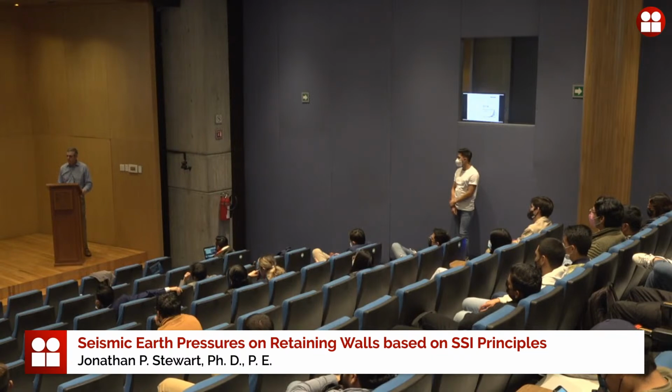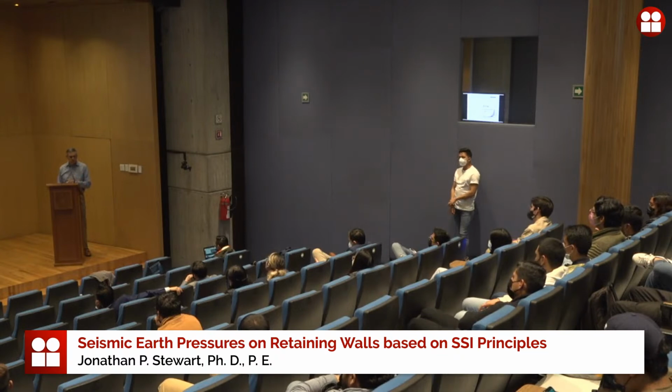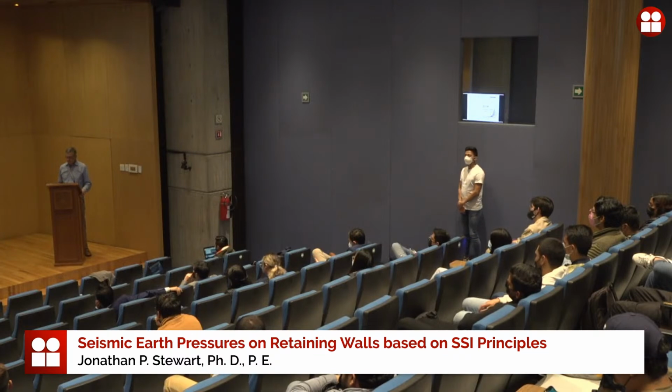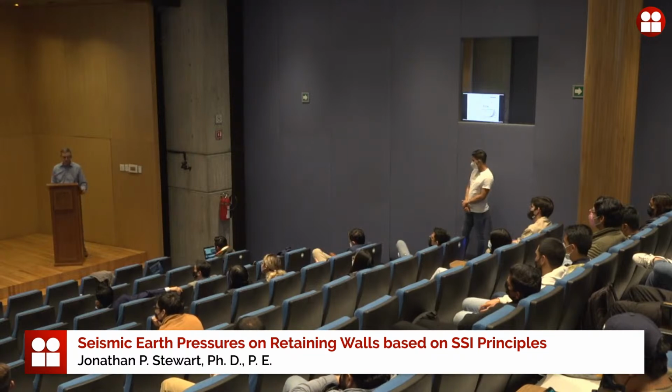The level of resolution in the Davis test is better because it's a much larger centrifuge, so it's easier to get these sensors in there. You can use larger ones. And of course, in the green symbols, there's no uncertainty. It's a simulation result. So for the uncertainty in the red symbols, our best answer is that it's experimental data scatter due to these strain gauges that measured the curvature.